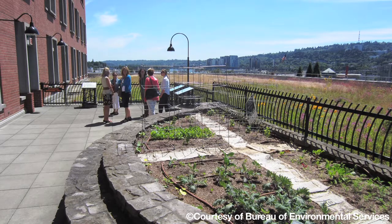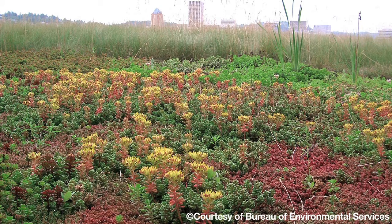There are several crucial landscaping components that help to make the project a success. The growth medium is a proprietary aggregate from a local company. The 6-inch soil is comprised of pumice, perlite, digested fiber, and reclaimed paper pulp. The medium has a higher proportion of mineral content than it does organic content. The composition meets the structural requirements of the roof and is free draining to promote plant growth.